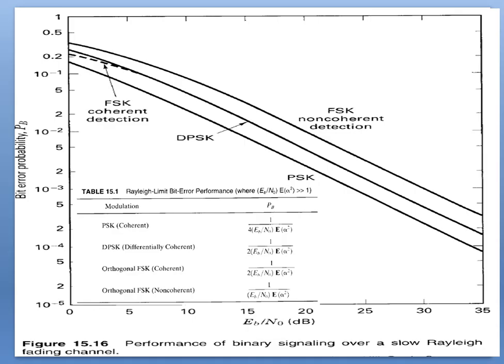We also covered time variations of a channel caused by motion, the basic fading mechanisms independent of each other, the concept of duality, degradation categories due to time variance viewed in the time domain, time variance viewed in the Doppler shift domain, and the analogy of spectral broadening in fading channels, degradation categories due to time variations viewed in the Doppler shift domain, and finally performance of slow and flat fading in a Rayleigh channel.